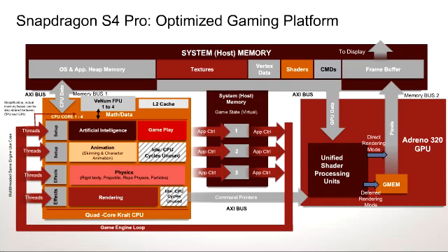On the right side, you can see Adreno GPU, which includes unified shader architecture, which is efficient for shader processing, as I explained before. And there's also an internal tile buffer, which is mentioned here as GMEM or graphics memory, which is used for a deferred rendering architecture or deferred rendering mode, which saves additional data transfers between GPU and system memory, which actually hosts the final frame buffer. So it does save a lot of memory bandwidth over there. So that's another optimization that is depicted here.